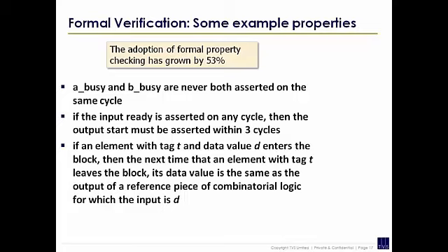The way it works, if you think of the simulation space here, you start at reset, where all the register values are known. So everything's in a known state. So you've got a single state because everything's known. And on the first cycle, after a certain number of inputs, certain flip-flops, or registers, can take different values. So you start to get different potential values on those states.